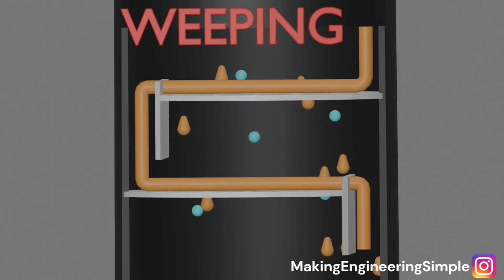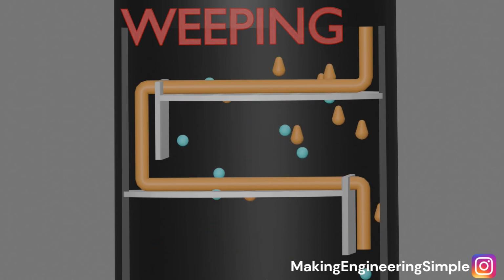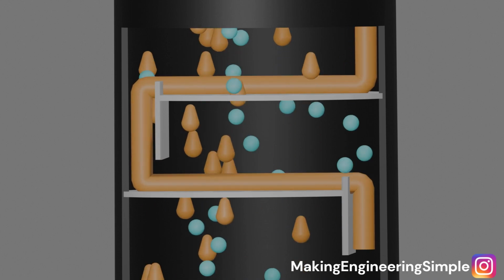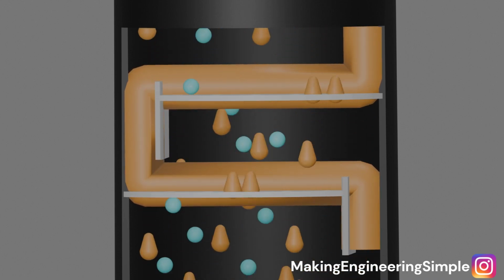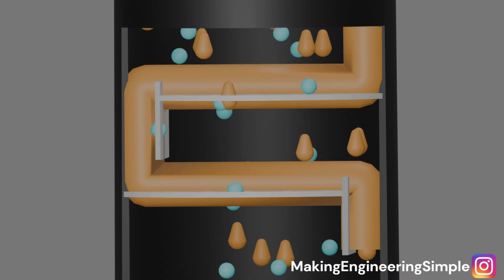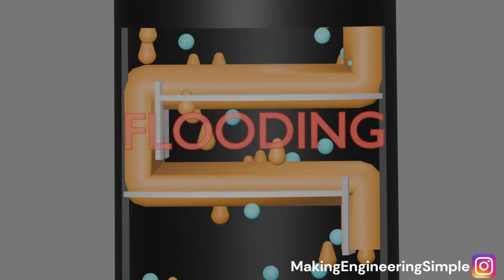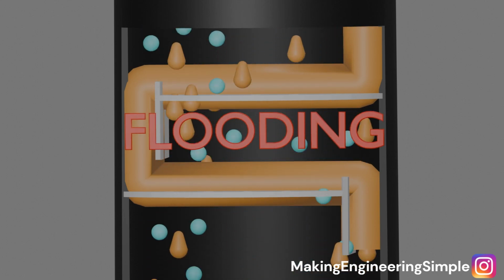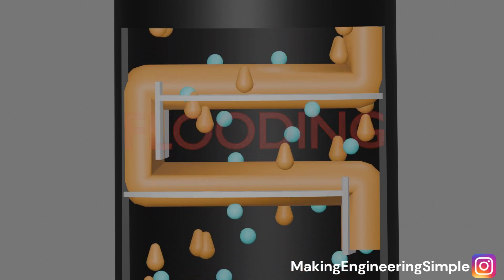On the other hand, if the controls fail and they blast too much heat, the gas shoots up so violently that the liquid can't fall down. The liquid gets pinned to the upper trays, and the tower literally backs up like a clogged drain. This is called flooding. When a column floods, the liquid gets carried straight out the top, destroying the purity of the overhead product. It's a catastrophic process failure that can shut down a multimillion-dollar plant in minutes.